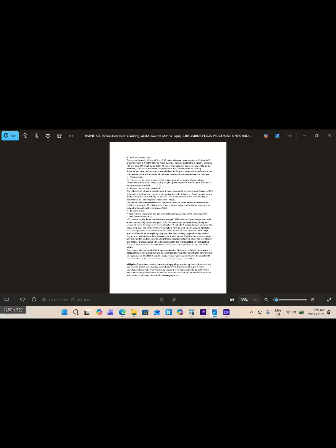The corrosion of carbon steel increases with temperature at constant acid gas loading. Temperature limits vary from plant to plant, but generally should not be higher than 125 C for carbon steel material. So this temperature threshold is very important to avoid amine corrosion.